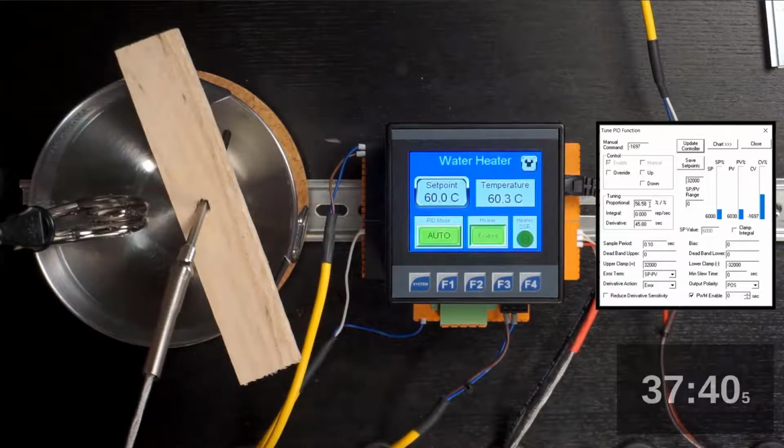In other words, from a CV calculation of 100%, how close to the set point do I want to be before that CV calculation drops below 100%? By the calculation I've made, if I have a proportional value of 64, then I'm going to keep that CV calculation at 100% up until 5 degrees before I get there. So basically what I'm saying with this long-winded description is the suggested coefficient of 56.5 is pretty close to 64.